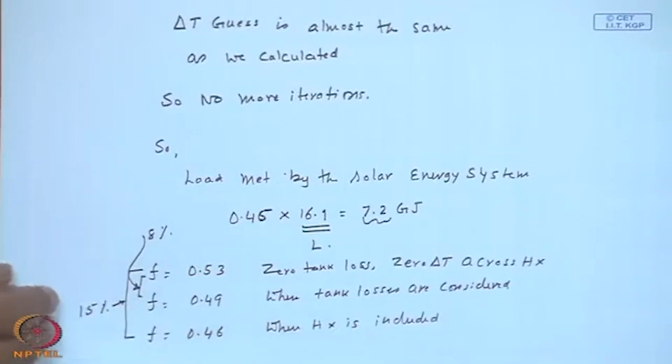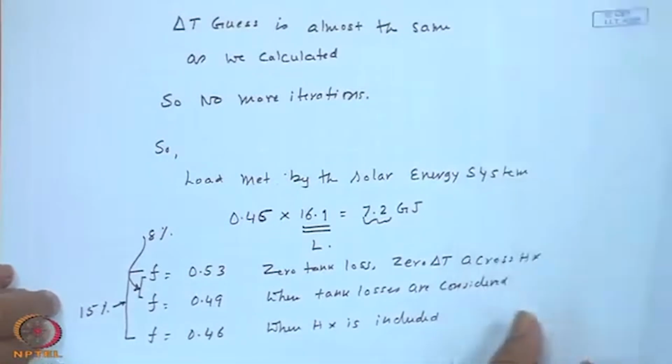Okay. So, this gives us a feel for the numbers. Basically, we have calculated the solar load fraction met for 1 month by a process heating system employing flat plate collectors of certain specifications at a location of latitude 40 degrees with slope of 40 degrees facing south, having a tank of UA 5.9 watts per degree C and a heat exchanger of epsilon L C minimum of 1350 watts per degree C.